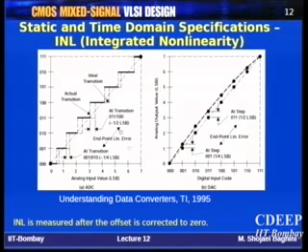If you look at a particular point, in DNL we are looking at two consecutive transition points and how these two transition points are different from each other. This is a real transition point, this is a real transition point, how these two are different. In integrated nonlinearity, at a particular transition point, we look at how much that particular transition point has been shifted.